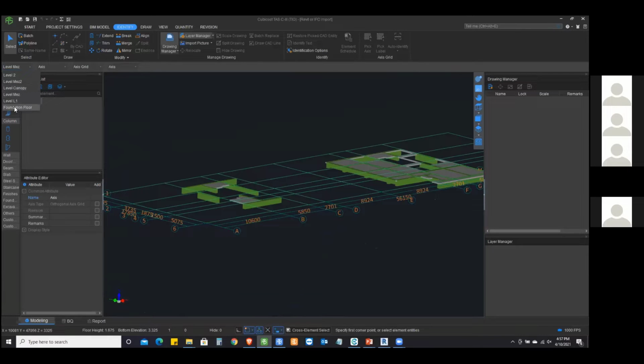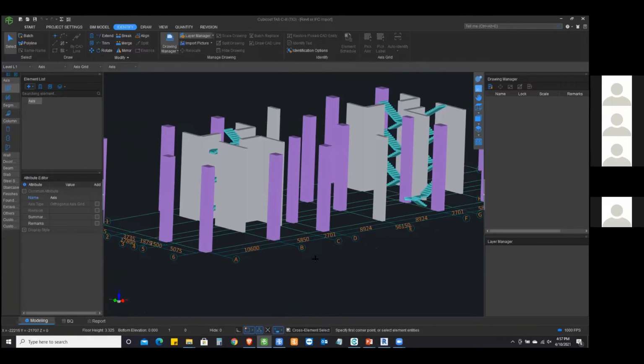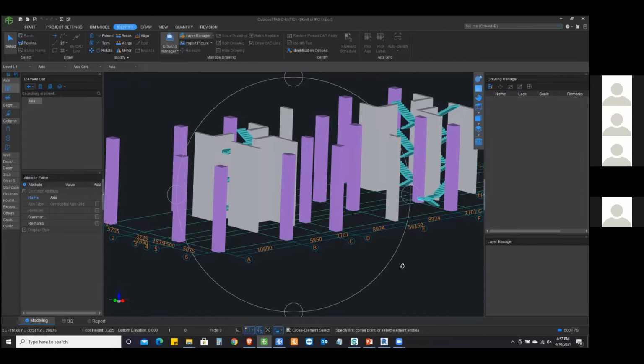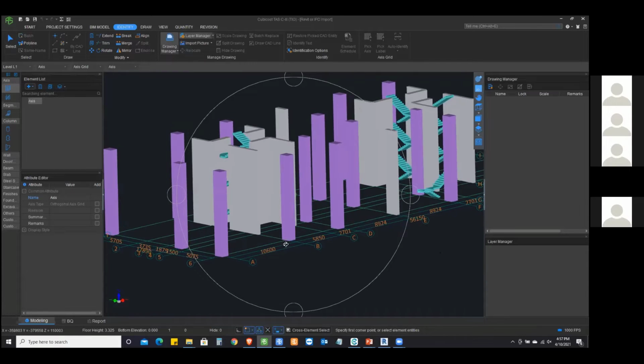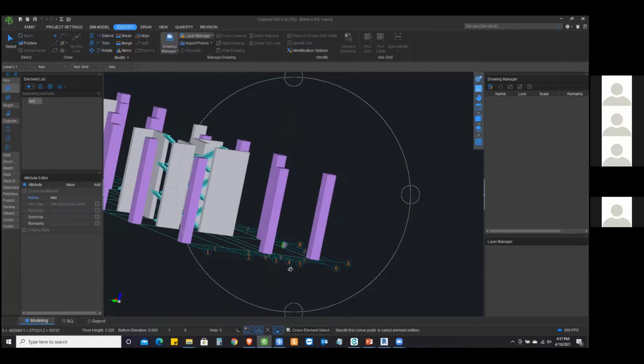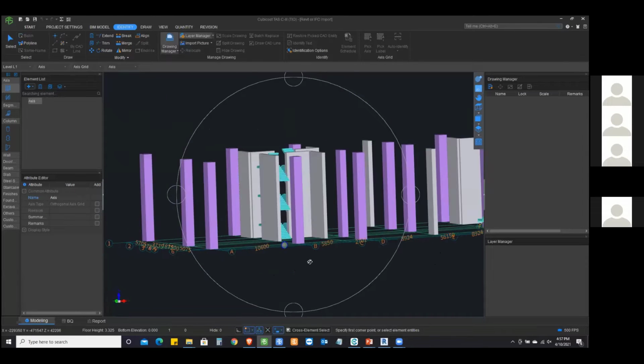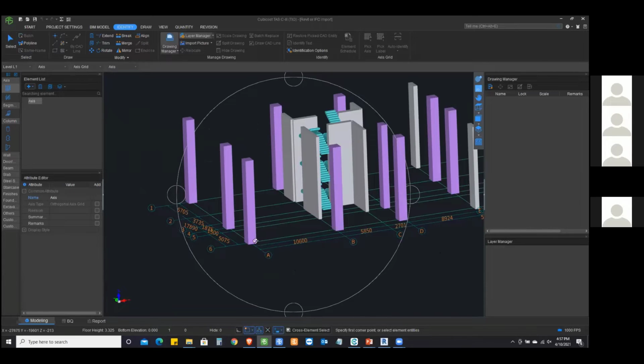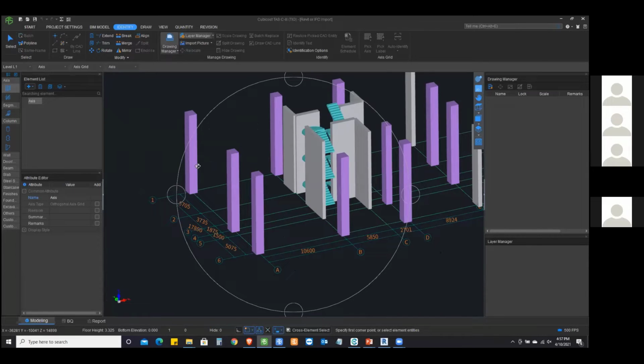The problem is that when somebody built up this beam model inside of Revit, they considered the column is going throughout the building. I mean, it's going all the way up, and that is the case in reality, but then it is recommended to cut it down into different floor levels in order to get separate quantities inside of your task. So that didn't happen because of the modeling problem.